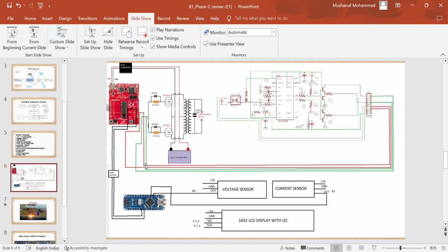Simultaneously, we write a program that will stabilize and fractionize the input values from the voltage and current sensors, and produce a readable output display on the LCD, as well as generate a high or low pulse for the SG3525. It will generate pulse signals depending upon the feedback values. The outputs of MSP pins P2.4 and P1.6 go to the PC817 optocoupler.